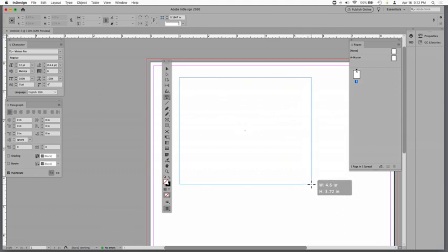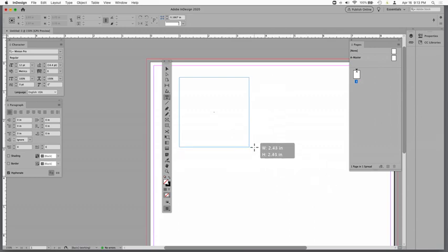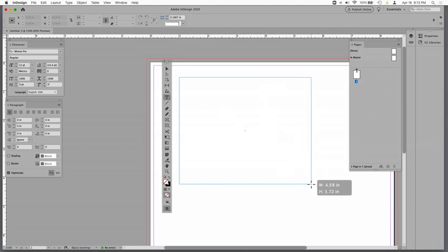Graphic design tools oftentimes utilize your left hand to do certain keyboard actions in order to make your work a little bit more efficient. I want to teach you some of those as we go along. This one here is holding down the shift key. If you hold down the shift key while you left click and drag, it will form a perfect square. You can see the dimensions of the box expand, with the ghost window there. If you let go, it continues to make a rectangle in any shape or size that you like. I'm just going to let go here.